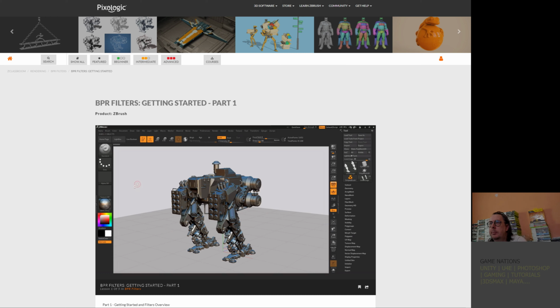After that, I want to change the material that's applied to the mesh. So currently there is this Ma Shiny Matte Cap applied. And I want to change the material to a flat shade material. So one that is using a standard material that will allow me to change the lighting information and have it reflect on the model. So I'm going to load one material that's in Lightbox.